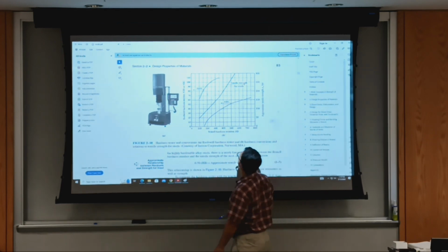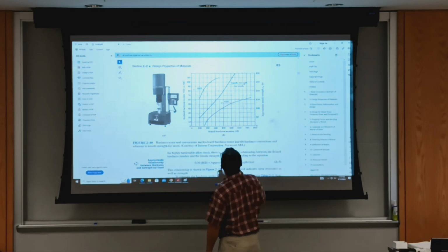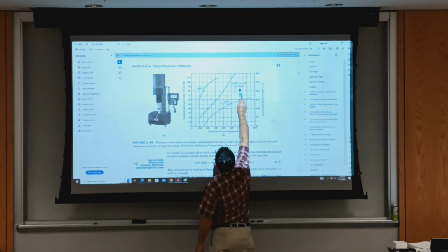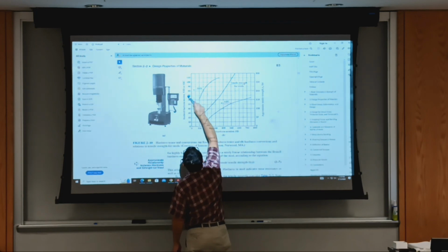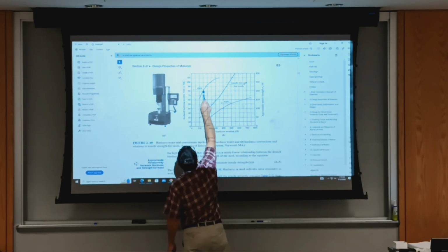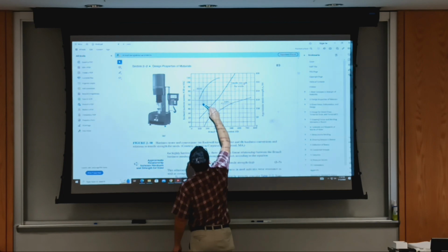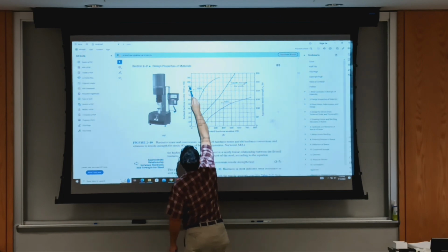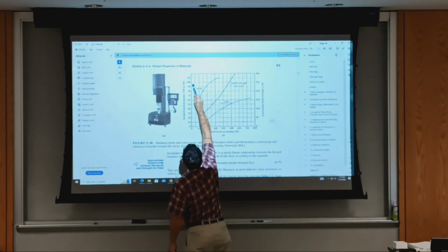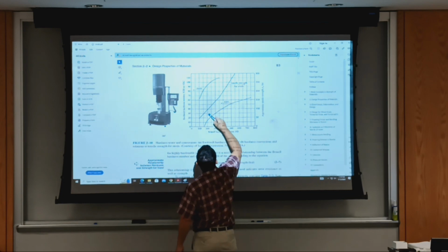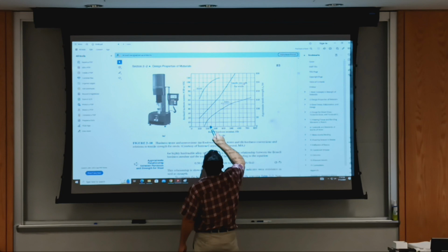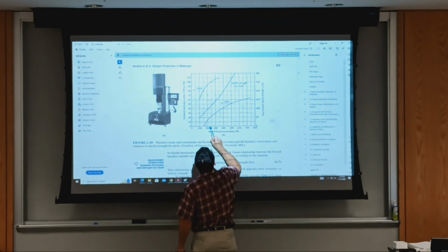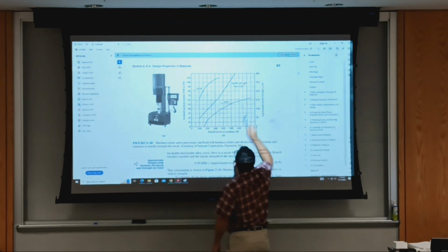And what would you do? Well, you need to move to this curve. So say I have 80 Brinell hardness B, you need to go to, well, 80 is too little, let's say 90, maybe 100, okay. I go to Brinell, and then from Brinell, go in this way.